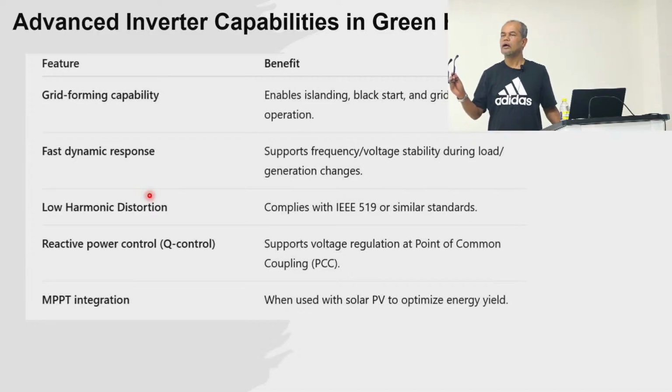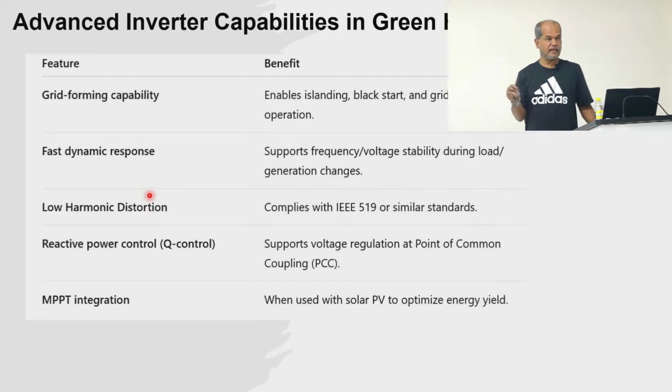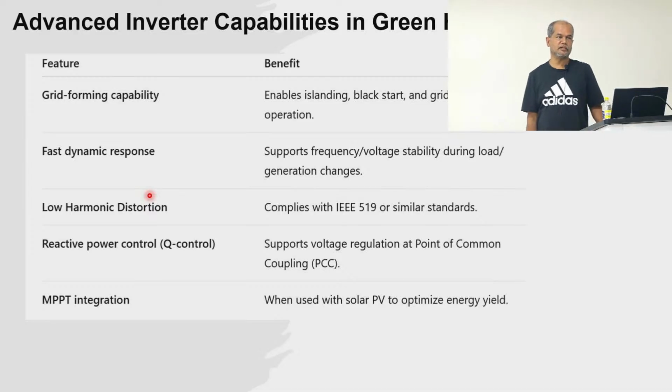So before applying it to the inverter, we might boost the voltage first, and then we convert from DC to AC. In most cases, we'll have a single device, which is the combination of a boost converter plus inverter.